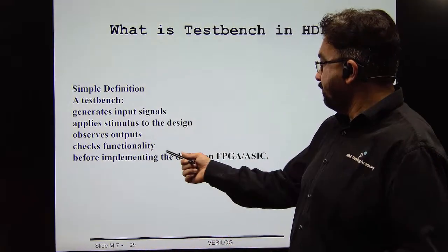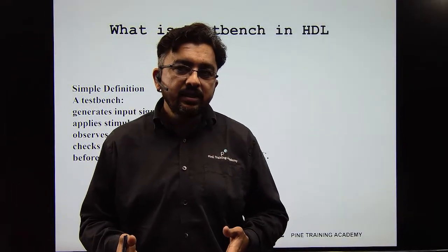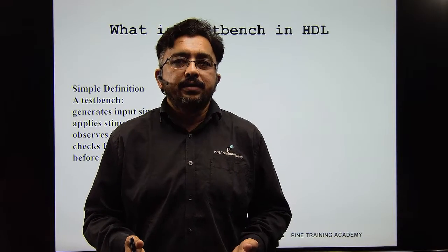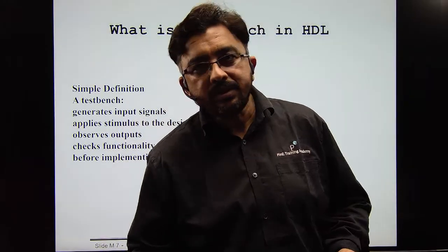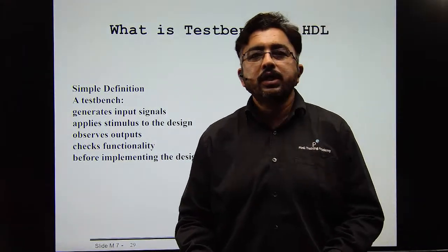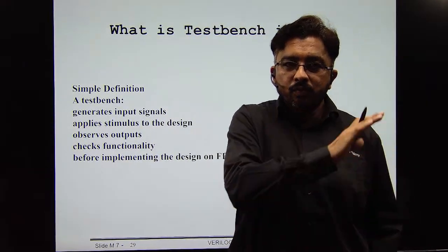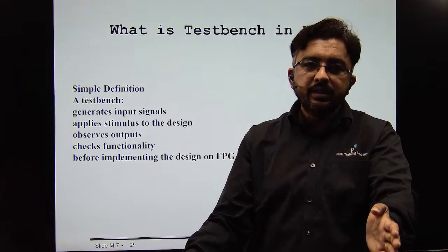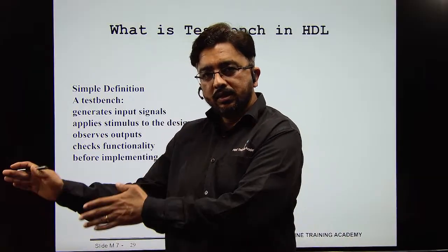Before implementing the design on FPGA, whatever we are designing, ultimately we have to convert into hardware, that is, some gate level netlist. If we don't convert the design into a gate level netlist, you cannot run anything on FPGA. So in an engineering team there is a small verification team, on the FPGA side, not the VLSI side.